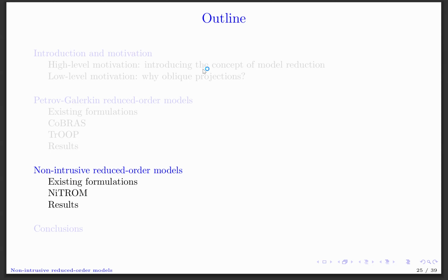Basically, you need to be able to linearize your CFD solver around time-varying trajectories, and you need to compute the transpose of that linearization. It's easier said than done if you have commercial software, for instance, where the underlying source code is proprietary. You cannot go in and modify it and extract the information you want. Or if you have legacy codes that are highly parallelized, like turbulent flow solvers, which are quite complicated to go in and modify to extract relevant information.